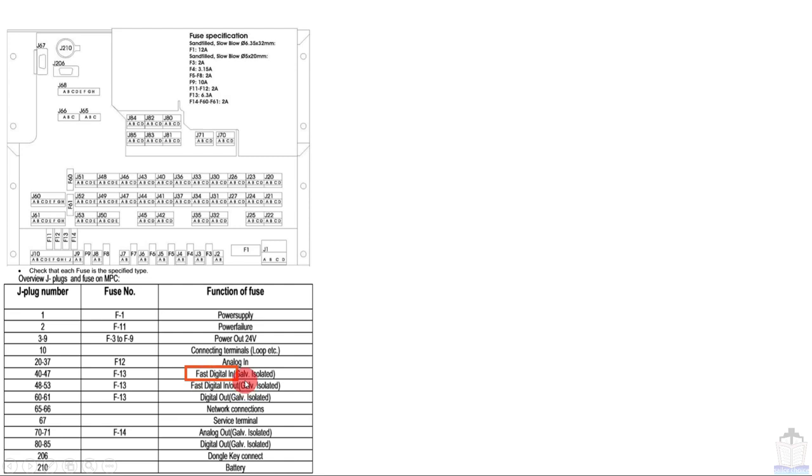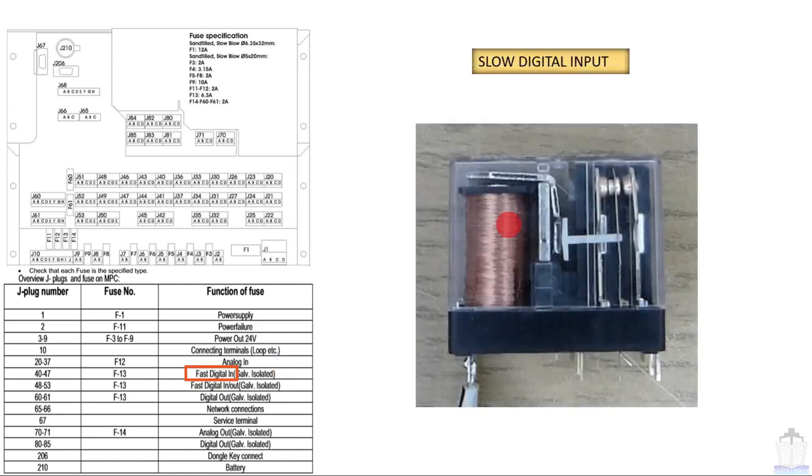that is fast digital in. Before talking about the fast digital, we first understand slow digital. Slow digital means any digital signal generated from the mechanical contacts are called slow signal. For example, if this is the relay which I have shown here in working condition, means making and breaking the contacts. So if I want to operate these contacts 20 times in a second, I cannot make it because this is mechanical. This has several mechanisms, and there are delay obviously.